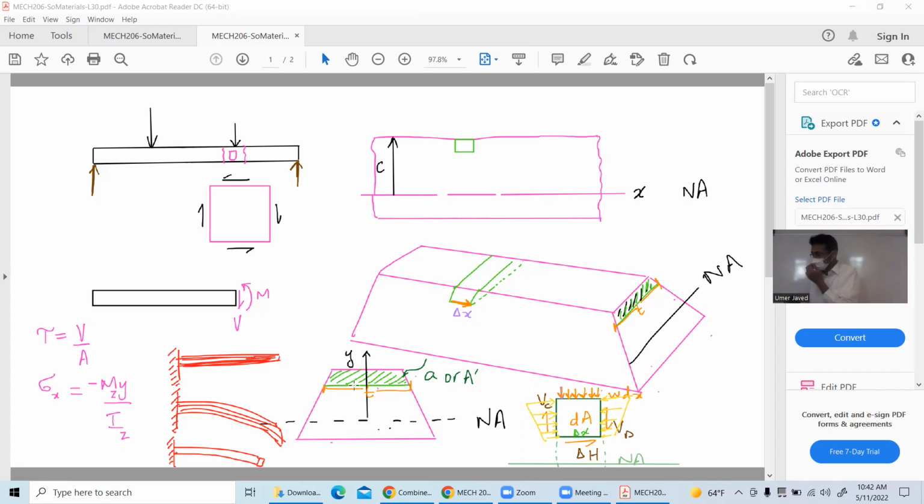Now, this is what you have to understand. Now you are saying why we keep on talking about these hypothetical scenarios. Oh, you want to talk about this shear. Let me tell you something. If I want to make let's say a beam that is made up of two different materials like this one, you see, so I have a plank of wood and I have another plank and I have pinned them together, right? Now, technically, I can use it to take loads. Just imagine if I am putting a load from the top, I have this bad feeling that the place by which they are connected together using the pin, it cannot sustain that probably, because there would be shearing between them.